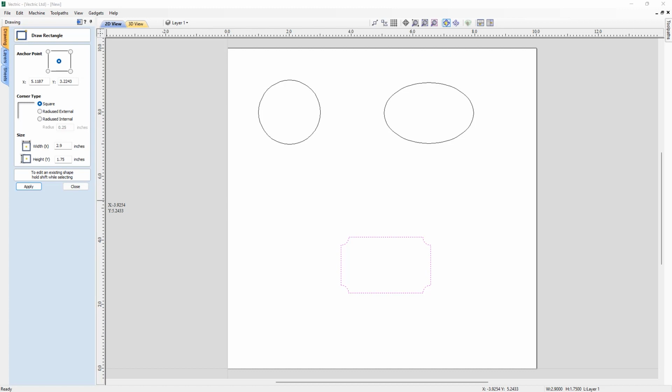So another way of creating a shape is by using the shortcut keys. So similar to how we did with the circle earlier with the diameter and the radius, we can create rectangles or squares based on the width or height, where you simply enter in your value. For example, if we wanted to make a rectangle that had a width of 4, we type in 4 followed by a comma, followed by the height value, which let's say is 2 in this case. And then we'll press enter on the key. And here we have a rectangle that has a width of 4 and a height of 2.